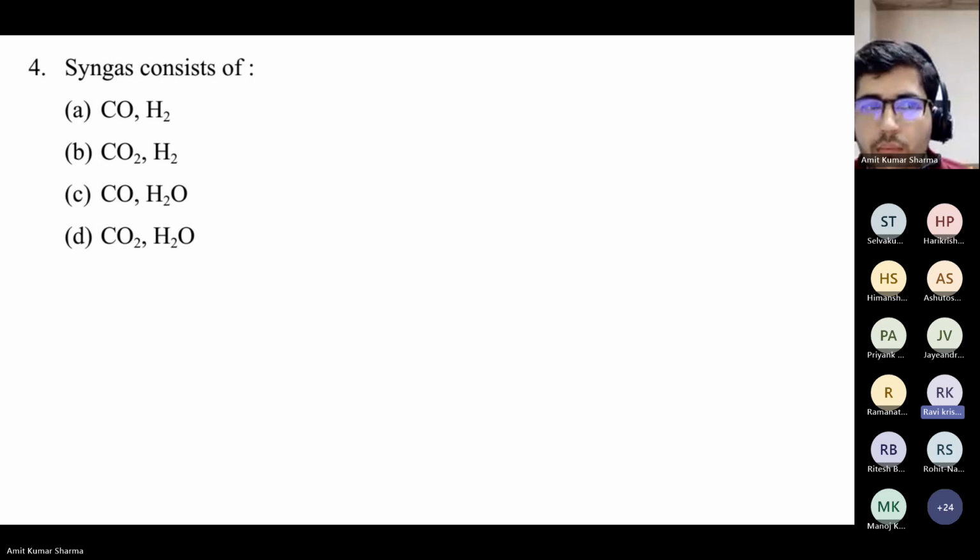Do you have a reforming reactor or a pre-reforming reactor? Reforming. We don't have pre-reforming, but we have a natural gas pre-treatment plant to settle out the higher hydrocarbons. Okay. So the life is 5 to 6 years for the reforming reactor with nickel catalyst.